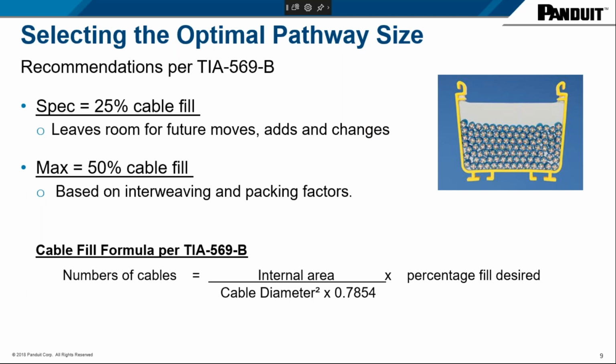And here is where I also wanted to highlight how we could continue to be that trusted advisor for our customers. We do want to provide recommendations on the pathway size that they should be looking at. So we like to recommend a 25% cable fill for the pathway itself. And you might be thinking, well, that's not very much. Why only a 25% cable fill? Well, we do want to consider the diameter of the cable. There are a lot of openings, as it's a circular diameter. So again, you do have a lot of openings between all the grooves.